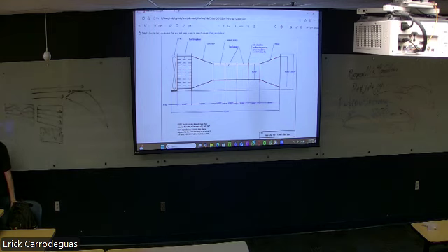That's gonna go into the contraction, and then from the contraction, here's where we start actually putting in our tools for measuring airflow, for measuring pressure, measuring all that. This test section here is gonna be one glass face, so we can actually see the airflow. We actually know what's going on inside. And then this last test section is just gonna be foam again. That's where we're gonna put tools to measure the flow as it goes out and all that.